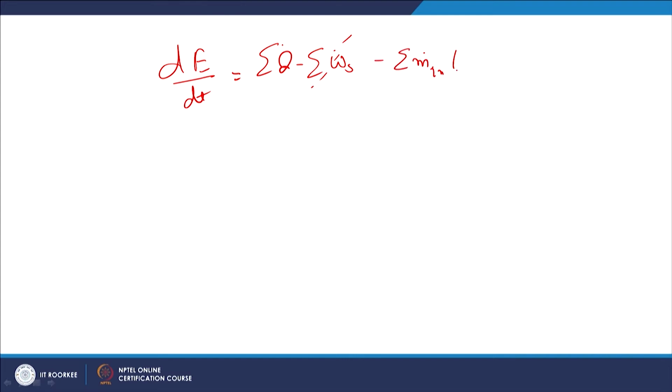We may assume steady flow, adiabatic conditions, and that the shaft work is 0. By applying these assumptions to our system, we get dE/dt equal to Ws, which is cut because we have assumed the shaft work negligible, then the summation of m_in (H plus EP plus EK) in.